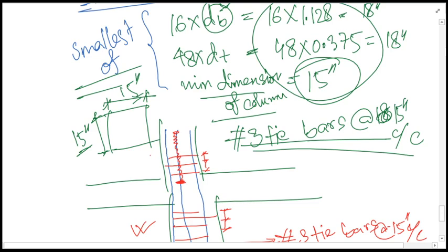But although there are some guidelines, you will also have to show these things here. In practical purposes, we cannot cut this close to the joints. After it exceeds the joint, then you can cut this one. You cannot cut just after the joint. And there are some guidelines. If you cut this particular reinforcement, you can cut it after exceeding a sufficient distance from this joint.